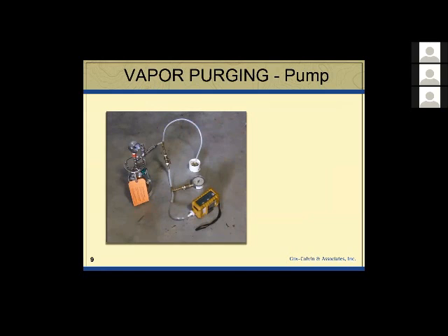So much for different sample devices. There's a lot of discussion in the literature concerning purging. You've got to get that clean air out of the sample tubing and the sand if you have a sand pack, etc. And you want to get good dirty soil gas in there. So here I'm purging with a multi-gas meter, the yellow device.